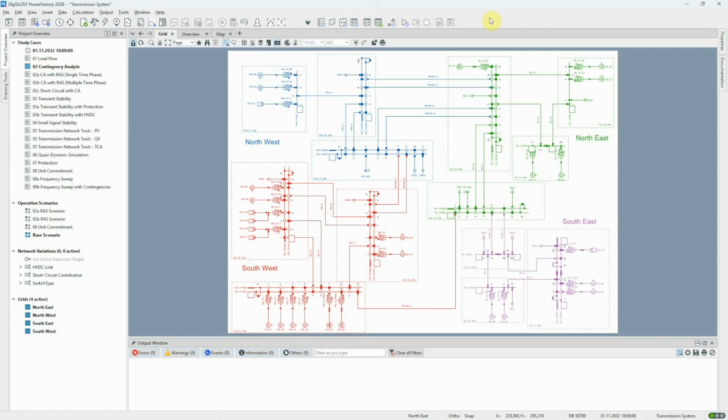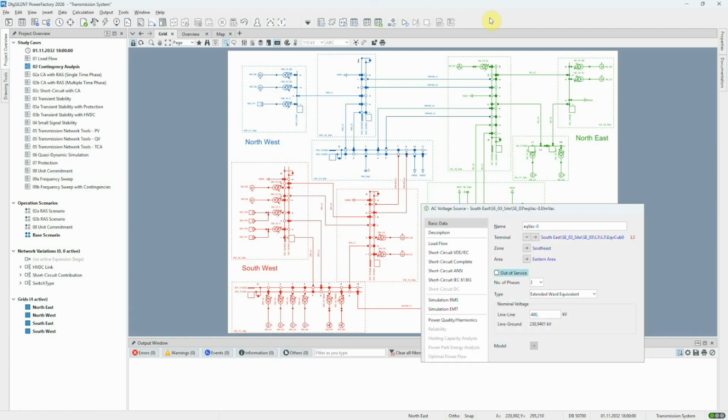When dealing with a large network model, it can often be the case that some parts of the network are of little interest for the purposes of a particular analysis or are of a confidential nature. Network reduction offers the means to remove these parts of the network and replace them with equivalent impedances and voltage sources. Reducing the network in this way also has the benefit of speeding up calculations whilst preserving the integrity of the solution.